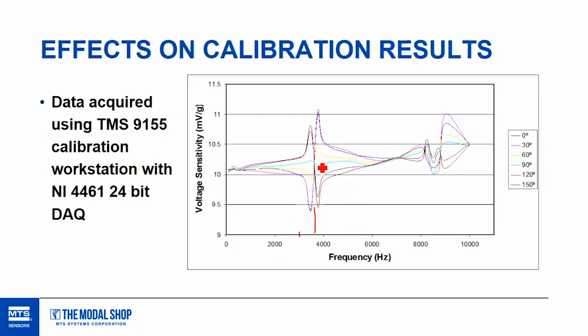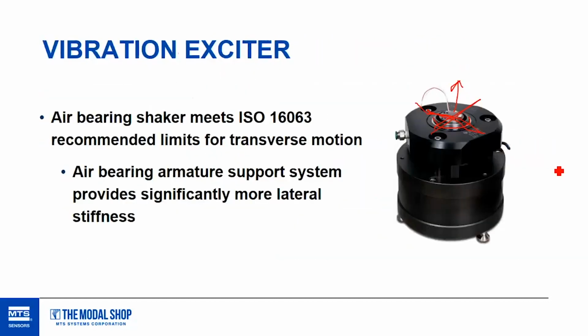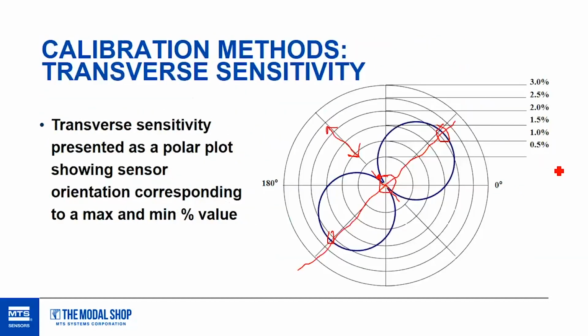So what's happening here in this turquoisey color, 90 degrees, right? There's a specific orientation that we ran into when we were rotating that around where we actually got a pretty flat frequency response on this accelerometer. And really what's happening, if we go back a few slides here, is just this plot here. That test accel, that teardrop that we're rotating, we're effectively rotating this blue curve here, this polar plot.